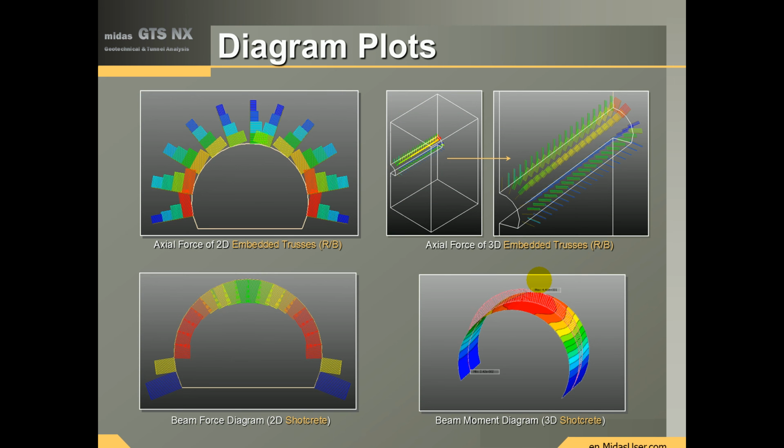We could do the actual forces and the member forces for the moments in, say, the shotcrete or the tunnel linings, also for the rock bolts, and we can even do the 3D shotcrete. So we can extract the continuous results for shell elements around the outside.